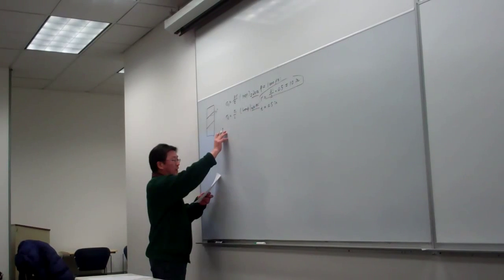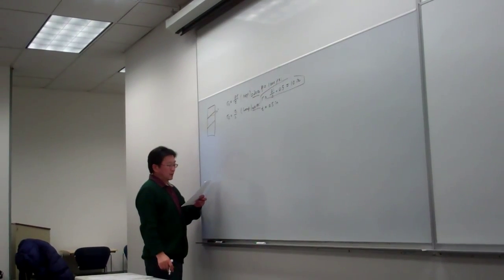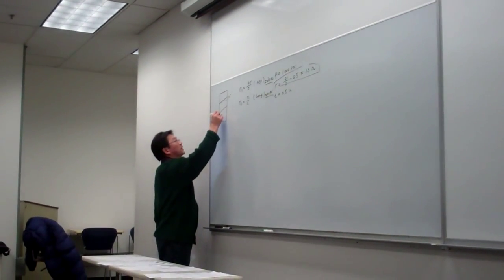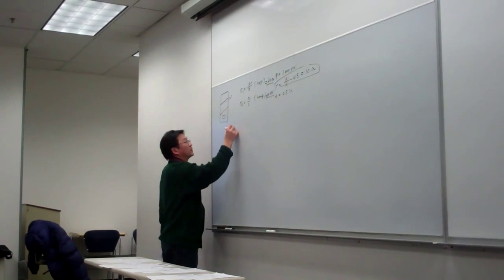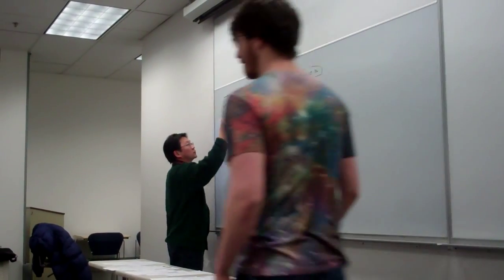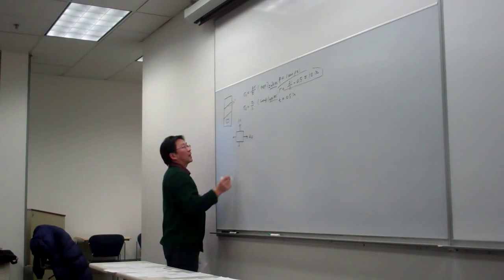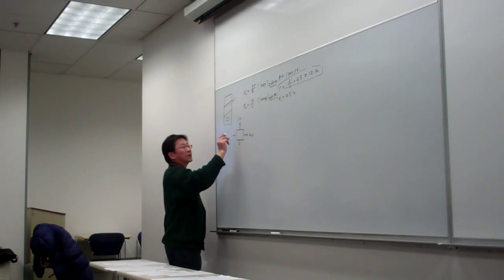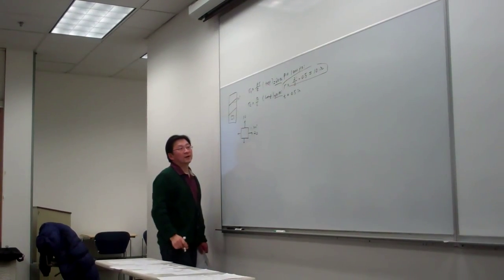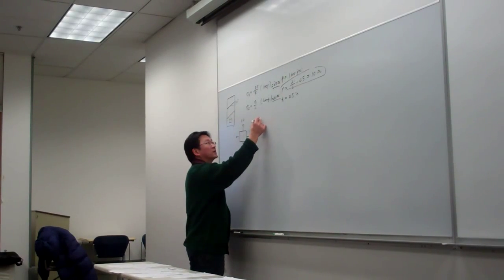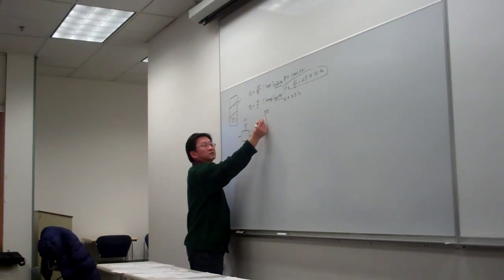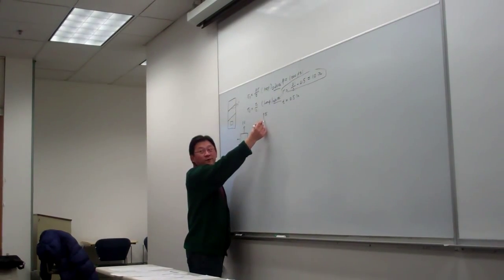For the second one, we want to calculate the stress normal to the welding. For this case, you can see right now, for example, we take the element like this, and the hoop stress is 20. The longitudinal stress is 10. And the welding is 30 degrees counterclockwise. So here, this is our welding orientation. The welding condition that we're looking for is the normal stress, normal to the welding surface. So that is the orientation we're looking for.